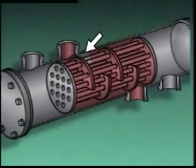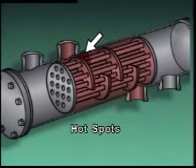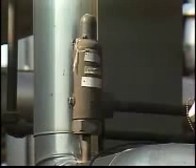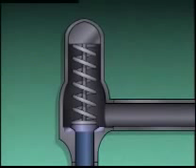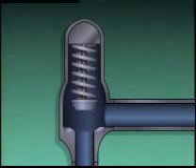These pockets reduce the heat exchanger's efficiency and can produce hot spots. A hot spot is an area in the heat exchanger where temperatures become excessive. These areas of high temperature can damage the heat exchanger. Another valve that's commonly found on a heat exchanger is a relief valve. Relief valves are used to prevent overpressurizing heat exchangers. If the pressure exceeds a preset limit, the relief valve opens to relieve the pressure.